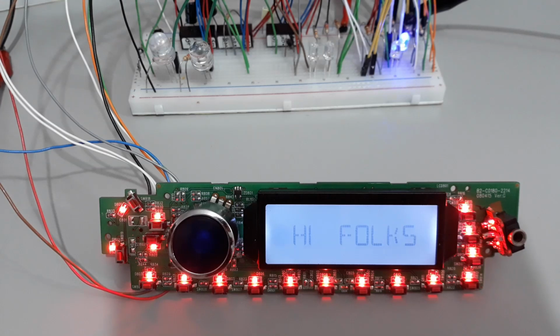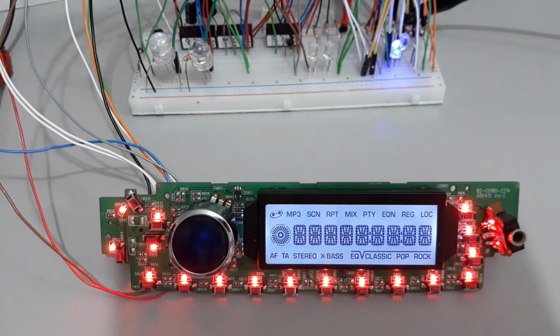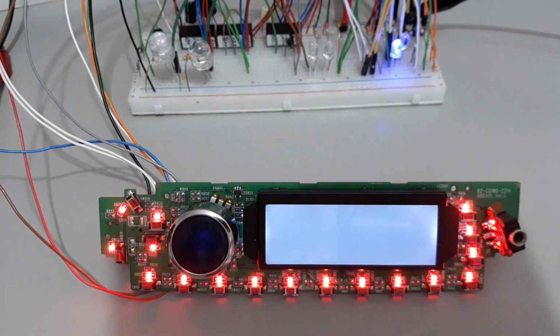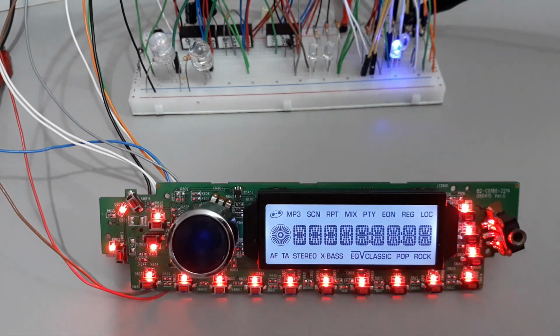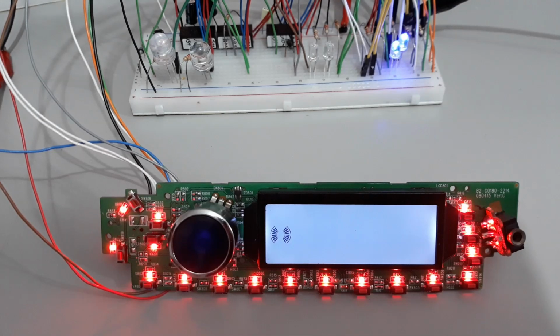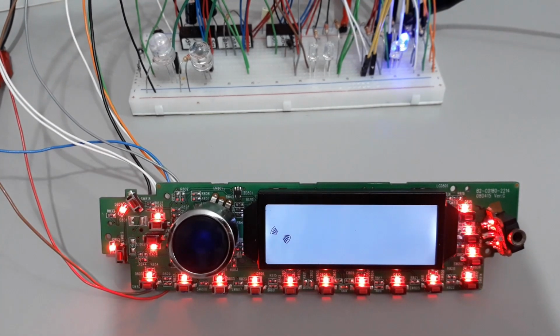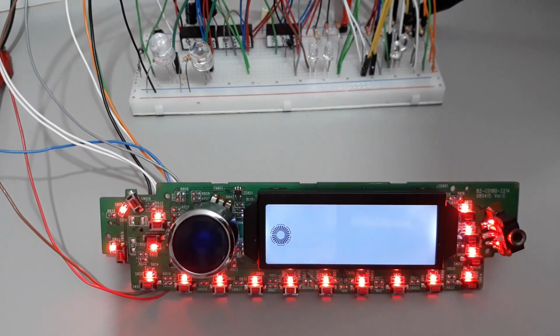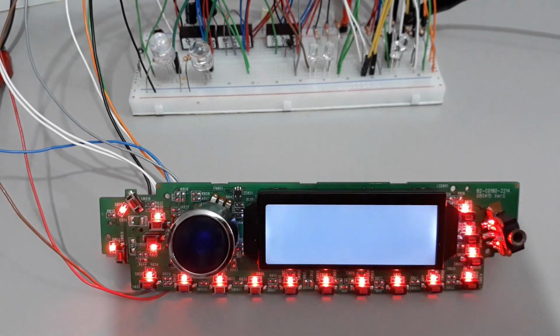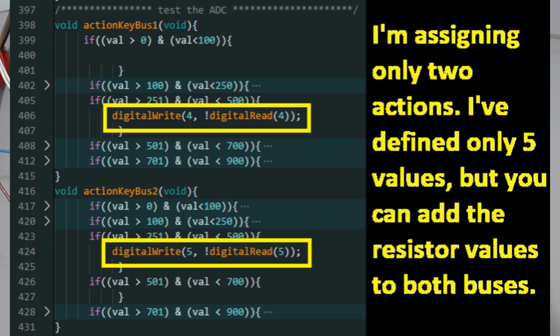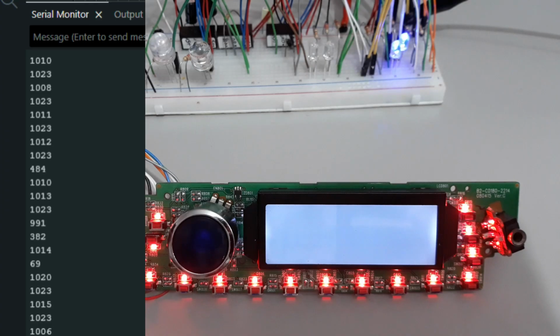The principle is 5 volts DC divided by 1024, equal to 4 millivolts DC. Therefore, in the worst case scenario, we will have a range of 93 times 4 millivolts, equal to 372 millivolts for each key in the reading of the pin connected to the ADC. Based on this range, we can now attribute actions to the interval values read at the ADC pins.